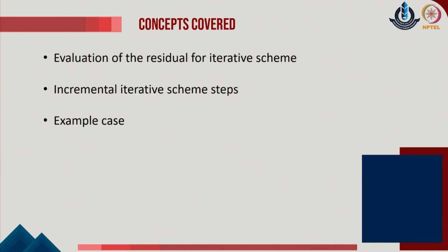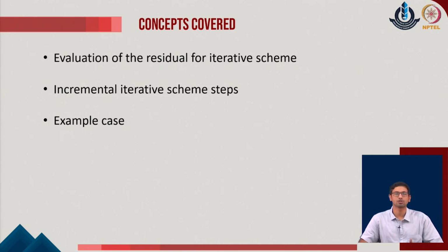What we have also understood is that, as we look at the given problem, the nonlinearity is introduced from the stress strain relationship of the material response, which is given in terms of the general internal variables of the system, which are the stresses and the strains. Whereas the general matrix approach or the analysis of the system is done on the overall variables of the system which are available at the respective nodes of the given problem, and those variables primarily happen to be the displacements or the forces of the given system.